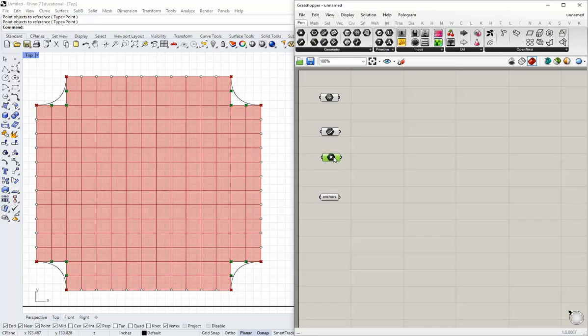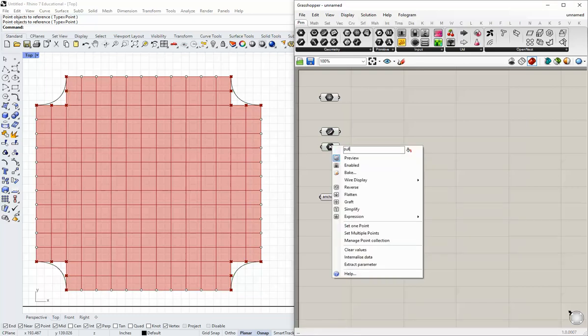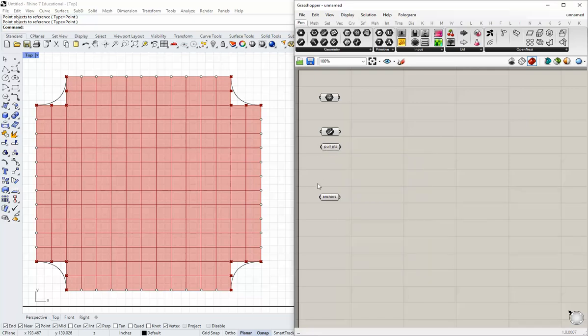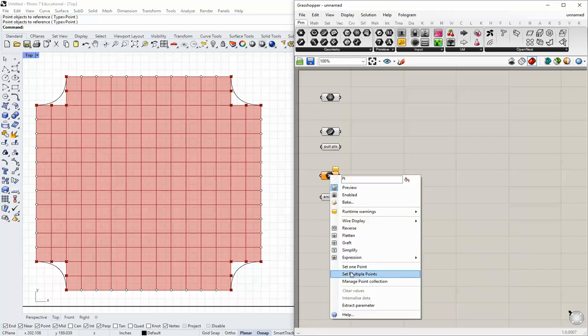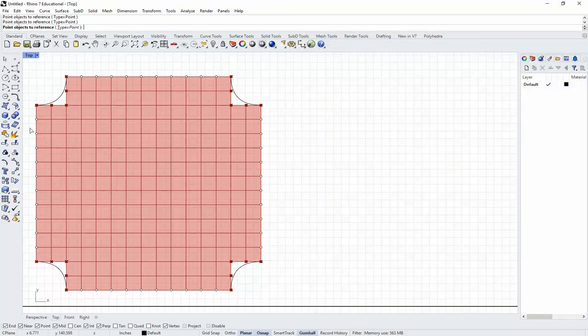All right, hit enter, and you now have a start at associating these points with those curves. There's one more step to do though. I'm going to call these pull points, so I don't get myself confused between the two types of points that I have here. And then lastly, just going to bring in those edge points as well. And here again, the order doesn't matter quite as much.